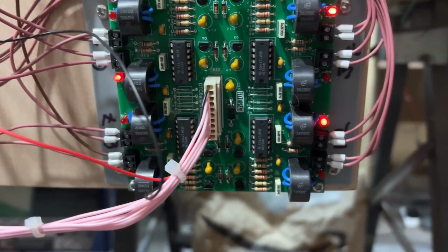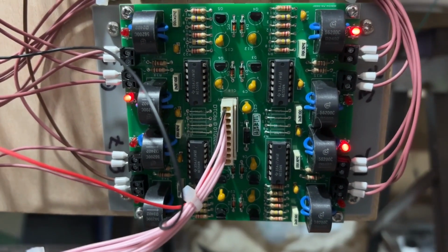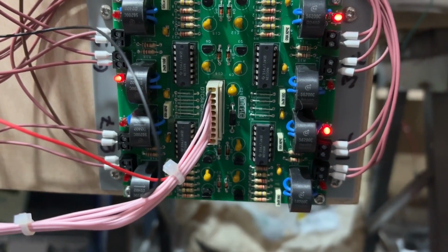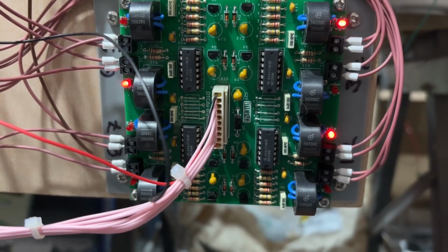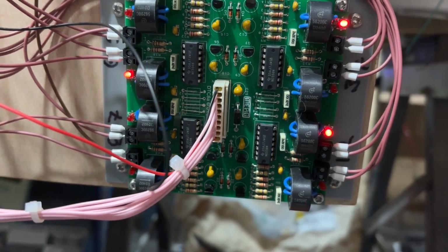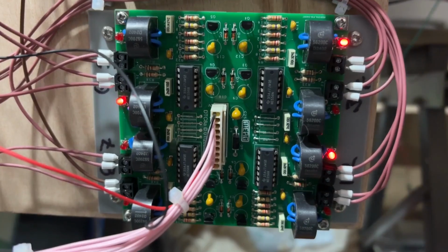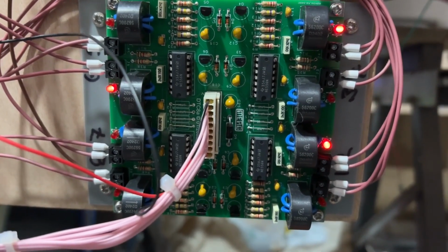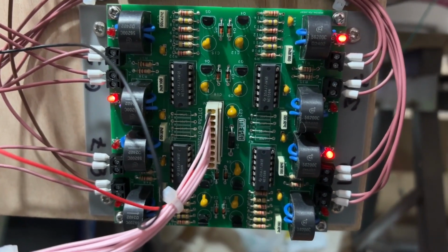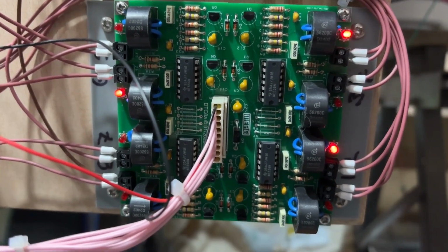So these MERG boards, and this is the reason I love these things, these are very, very clever, have these integrated circuits on there. There's 4 on there. These are timer boards. Now, if you've watched any of Train of Thought's channel, you'll see we've been playing around with the 555 timer, little astable circuit. If you haven't, it's well worth watching, actually. He's done some really good videos on it. Here, these are being used in a slightly different way. These are set up to run for about a second. So you give them a signal, and it puts an output out, and then about a second later it stops.